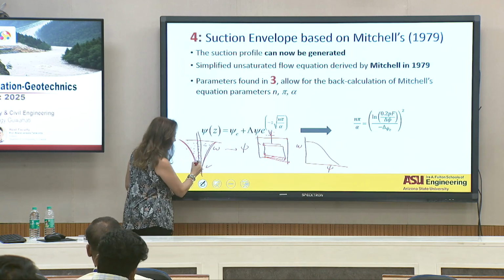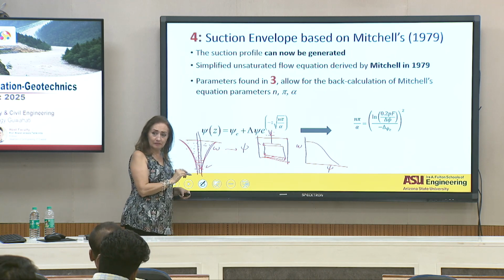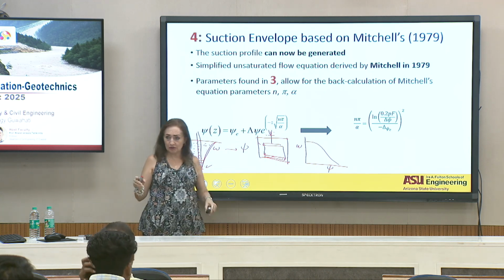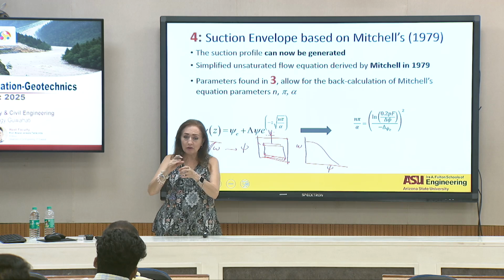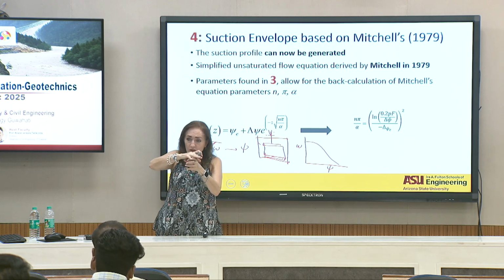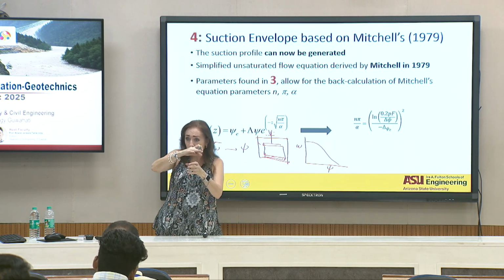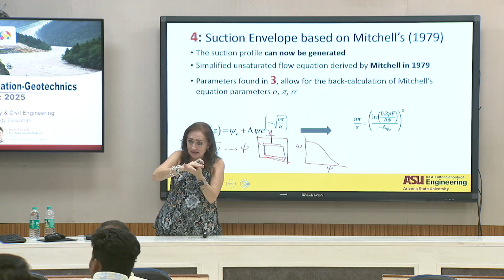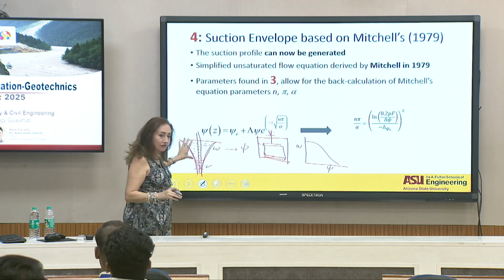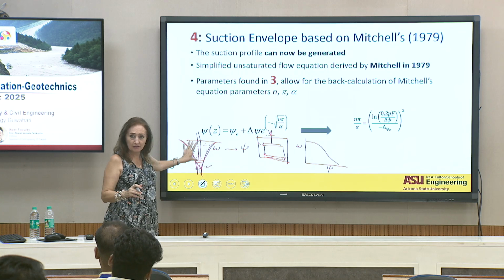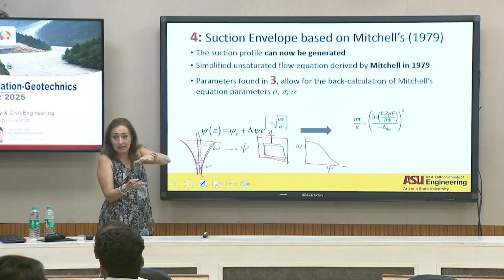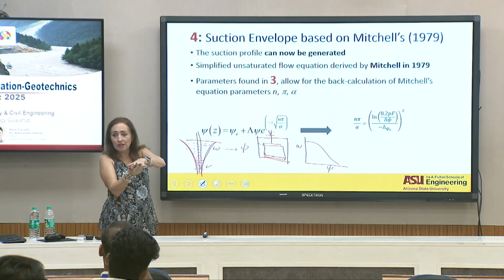You took it out from here. You took it to the laboratory, right? And basically, what you have to do is you need to consolidate or just load it again to the overburden pressure that it was experiencing in the field, right? So basically, you return the stress history to that point.